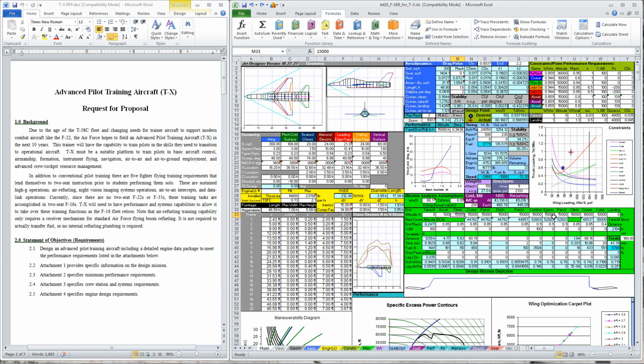The ideal situation would be to fly at 18,000 feet, be able to sustain that 6.5 G turn with no negative P sub S, and then stay right at 18,000 feet for the entire mission. And that'd be better for fuel burn. But if we design and optimize the airplane for the lower altitude, it should be able to fly the higher altitude version of the mission. Alright, so let's get started.